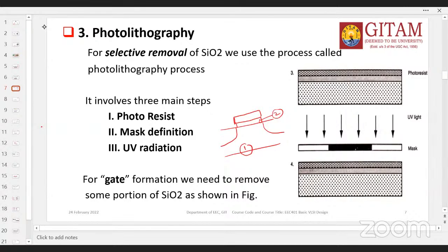Okay. The lower the thickness of the gate oxide, the better performance can be observed for the MOS transistor. So for better MOSFET operation, gate oxide thickness must be very, very small. Very small thickness is required. Agreed? If the field oxide is a few thousands of angstroms, the gate oxide is maybe 10 angstroms or 20 angstroms, something like that. That is the difference. Thickness is one difference.